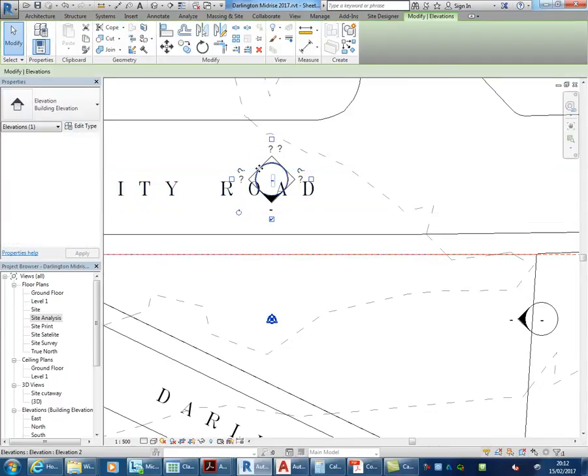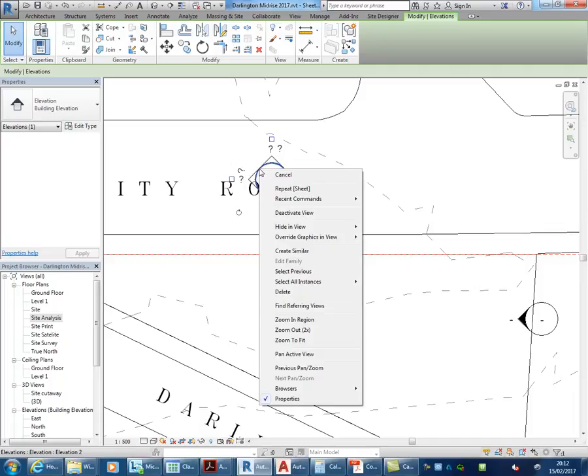Of course, the elevation views don't need to be there, so you can select one of them, and do you know the shortcut to hide category? Oh yeah, VH, exactly, that's good. So EH for elements, and then, spot on, VH to hide the whole category. And if you're watching the videos, you can right click and obviously choose hide in view category.